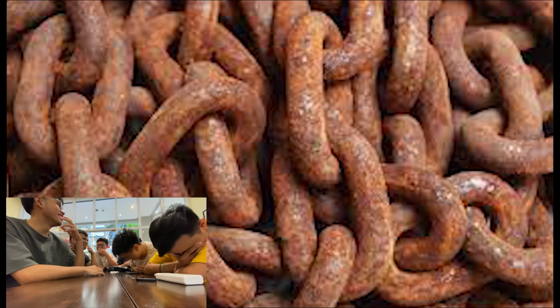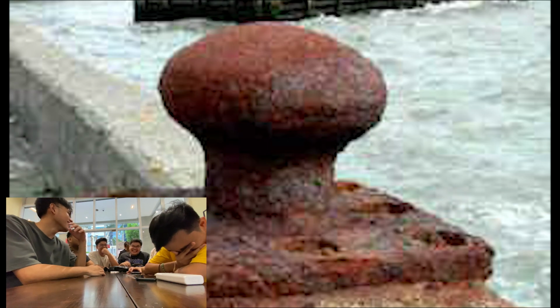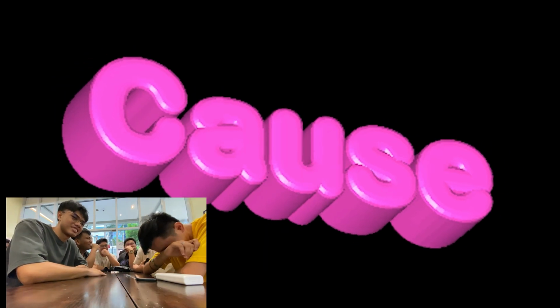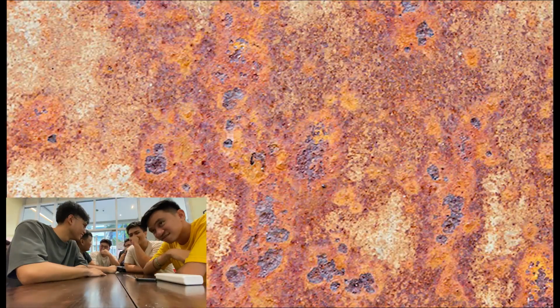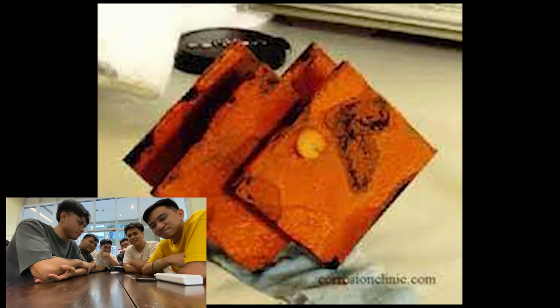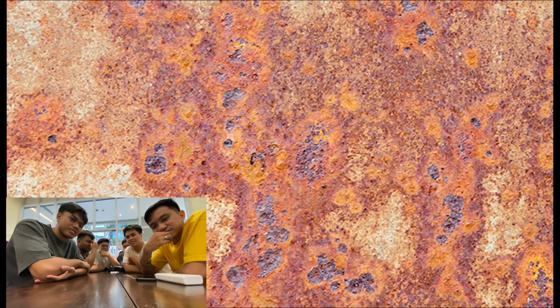6th, uniform corrosion. Uniform corrosion is the most common type of corrosion. It can be defined as the attack of the entire metal surface exposed to the corrosive environment, resulting in uniform loss of metal from the exposed surface. Causes. In natural environments, oxygen is the primary cause of uniform corrosion of steels and other metals and alloys. Detection. Uniform corrosion can be recognized by several visual and physical characteristics, including even surface degradation. The most noticeable characteristic is the even loss of material thickness across the entire surface of the metal.